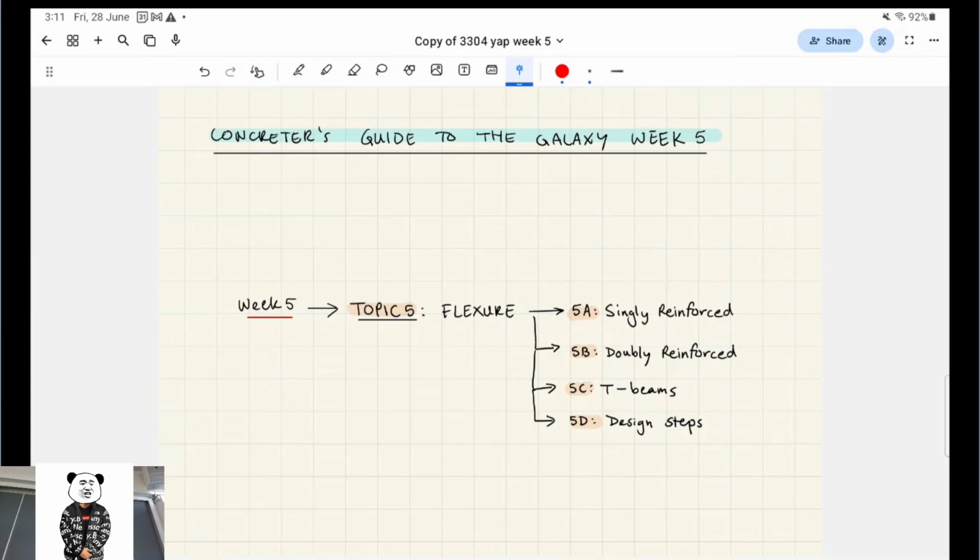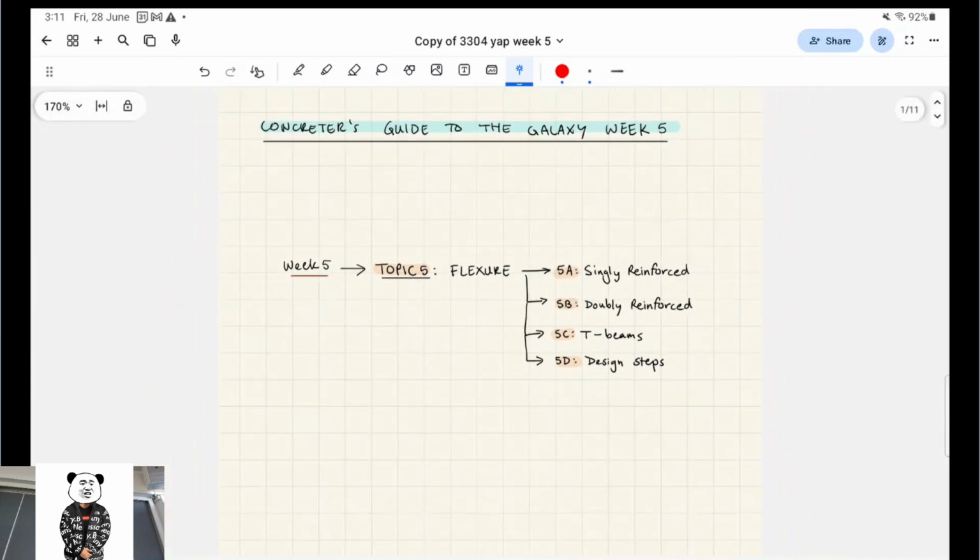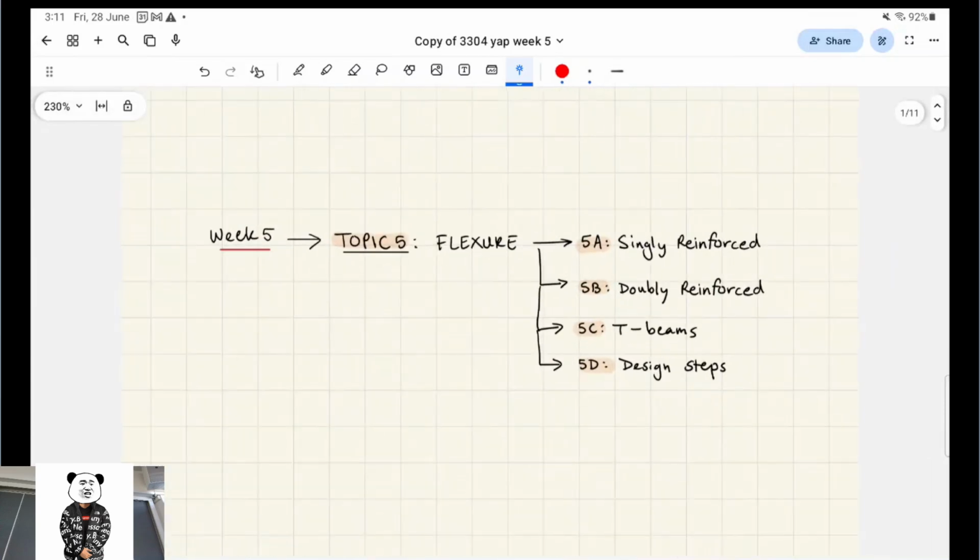But even for the steels people, this stuff isn't redundant information, because how we handle dead loads is going to be a little different in this course. We actually account for the self-weight of concrete, which we'll see in a bit. Whereas in steel, you don't really account for the self-weight of the steel. You would just call that part of the G or the dead load.